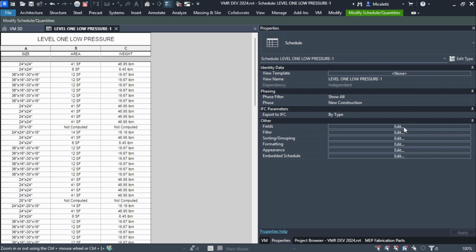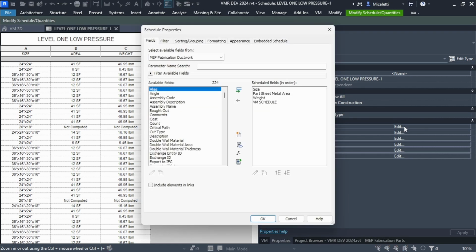Do you happen to have a template schedule for points that you'd be willing to share, or you don't have one set up? No, and the reason for that is it's based on whatever technology you're using. If you're using Trimble or Topcon, you will have to get with their rep, or even it's on their website somewhere. They all have documentation on how they expect their CSVs to be formatted. Yeah, we have Hilti's total station, and it's different than those other two. So basically what we've been doing is exporting to CAD and using the Hilti point layout software, which I think they have a plugin for Revit, but they make it difficult too.